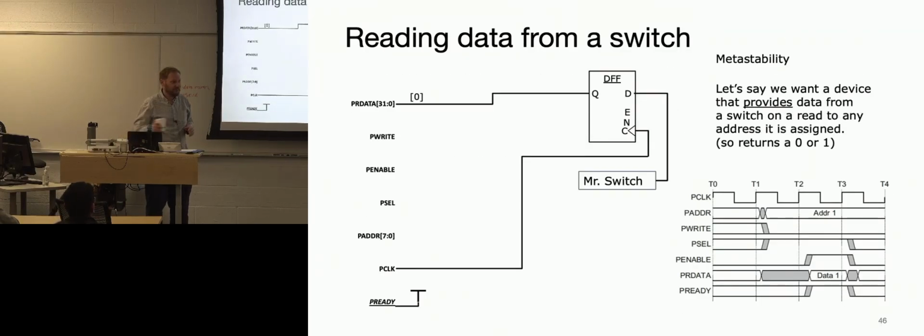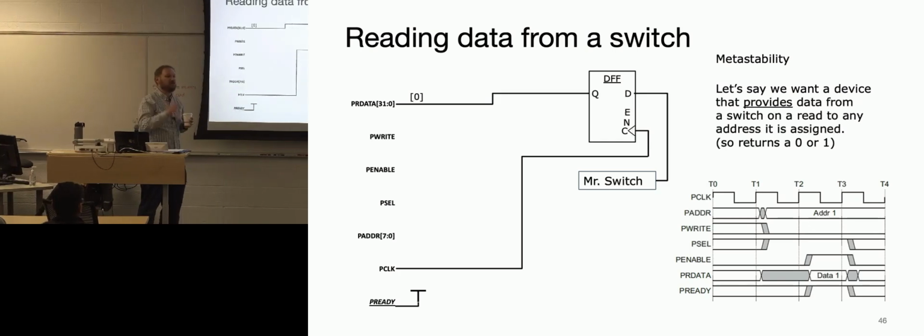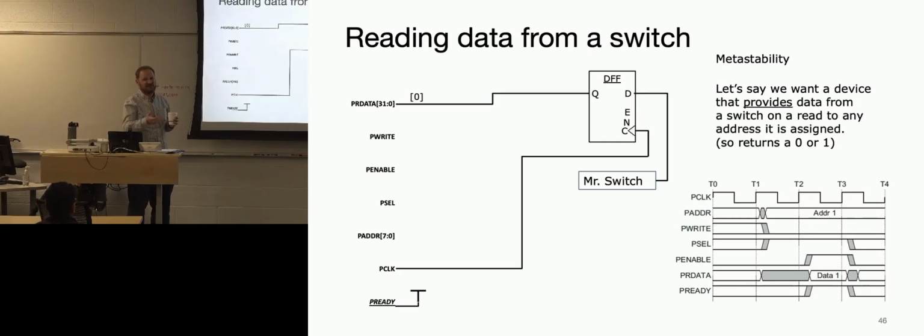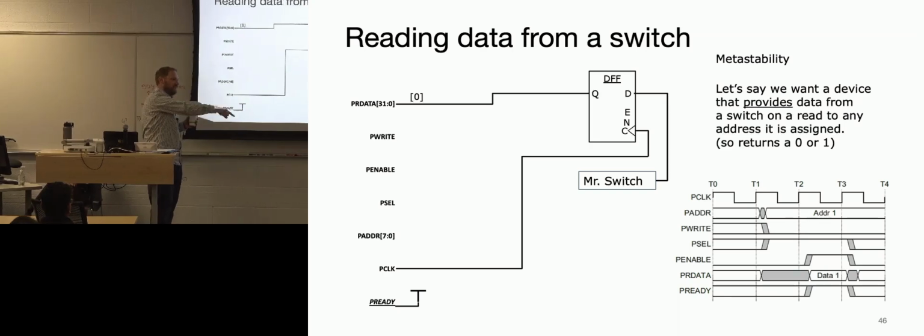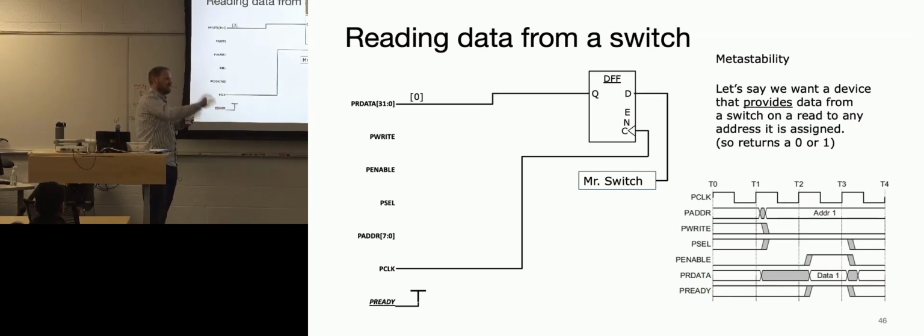Yeah? Is it possible that something's not ready immediately? Yes, we'll go over that example. That is the typical case. If you're just reading in and out of registers, they want to make it fast, so that's immediately available. But say you want to do something complicated like an ADC read, an analog to digital conversion. You say, take your analog, start the conversion, and send me back the value. Well, it may take up to 16 to 32 cycles before that thing gets completed.